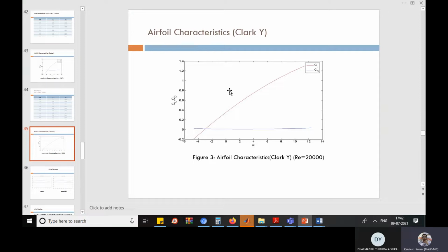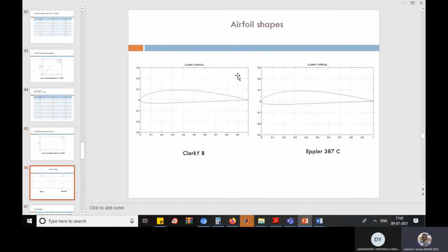And what is the maximum CL you are achieving, what is the maximum CD you are achieving, because a high CD is not good. You should have a very minimum, very small CD, so that is fine. But when stalling, you should not follow that particular angle of attack. Okay, so what we were talking about, you have to plot that. Let's get this first step.